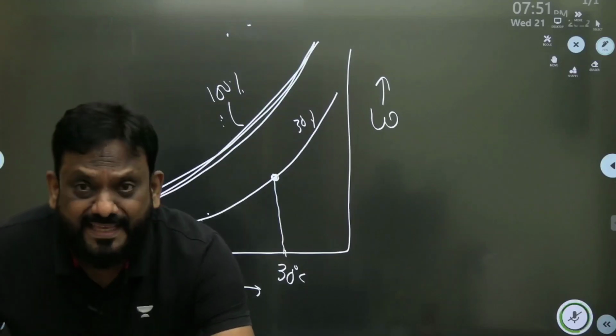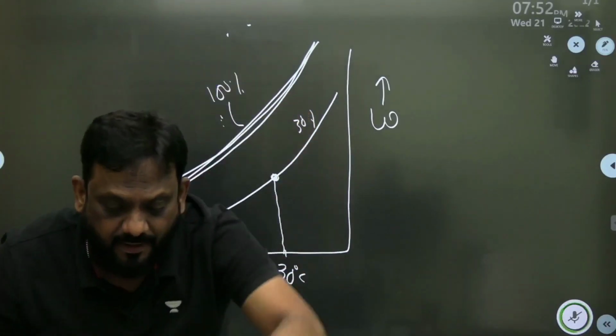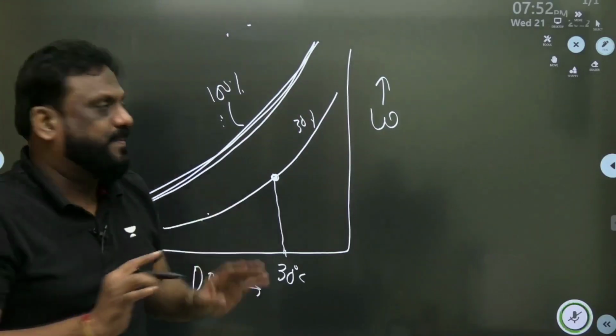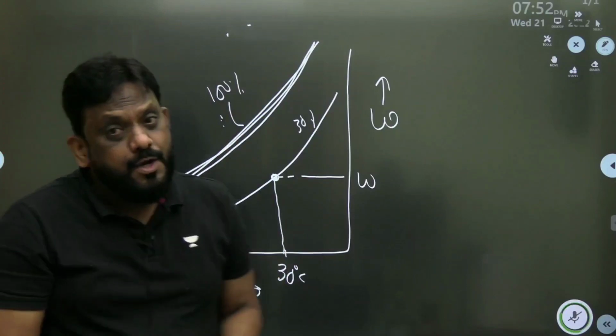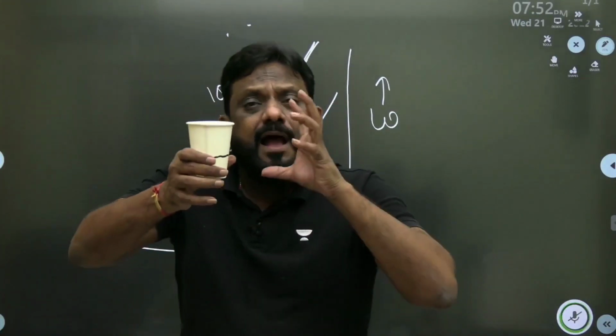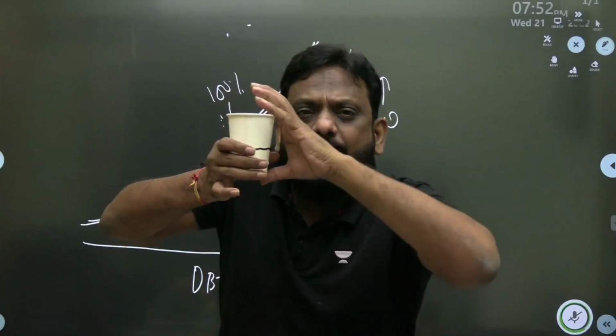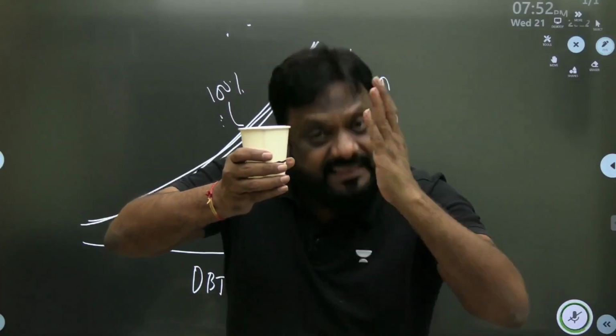Please note down that the actual water vapor which is present, we call it absolute humidity or specific humidity. This is the actual water vapor. Now what I do is, I will cool this. This is the absorbing capacity, or saturation, the full glass saturation condition at this temperature.